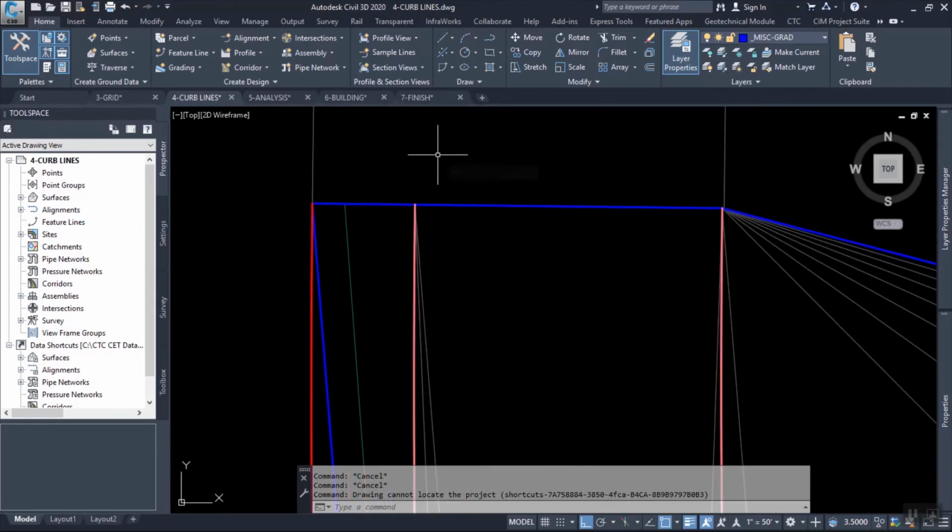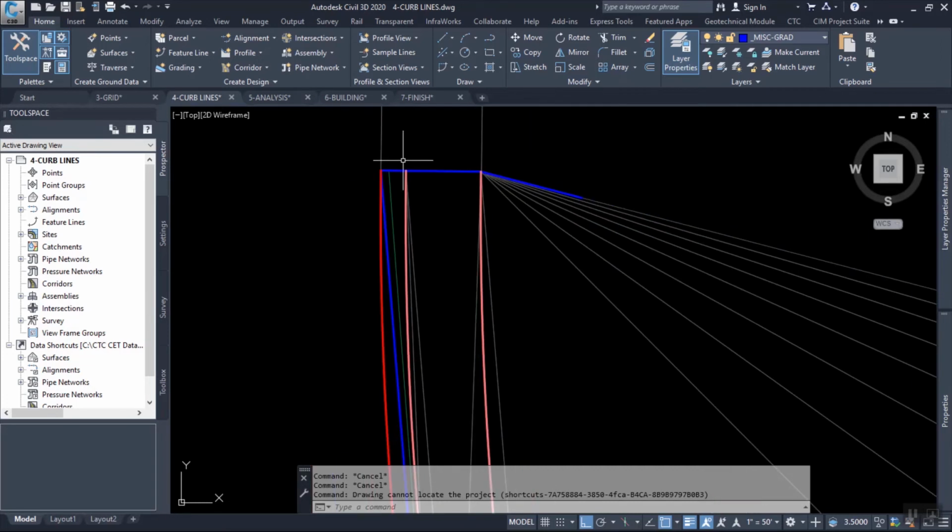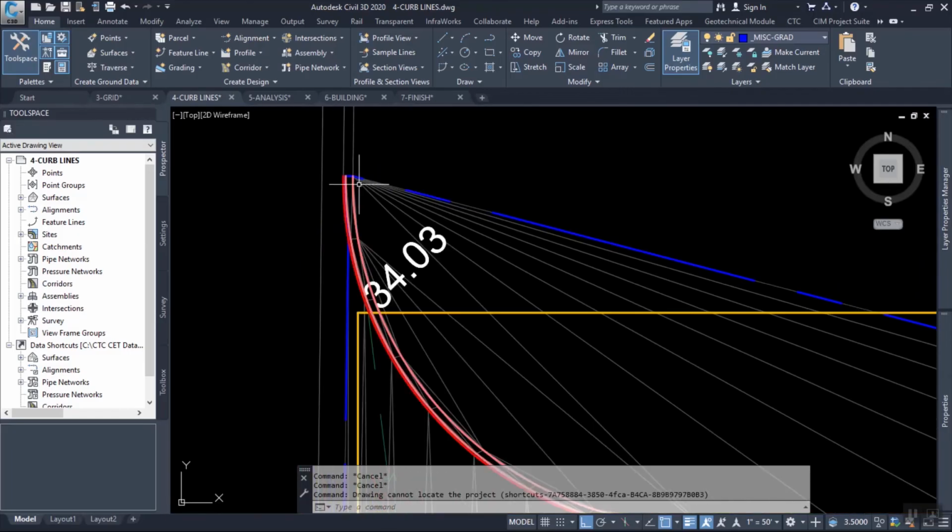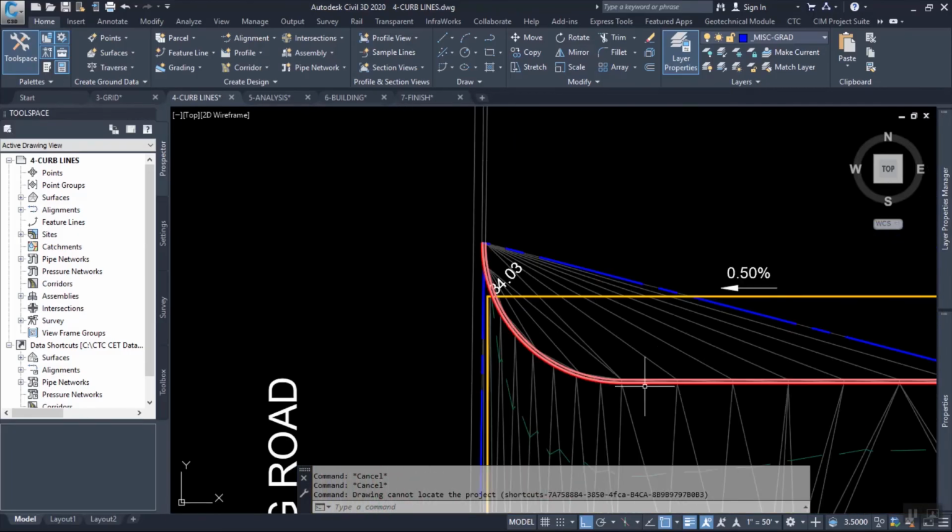If you have to do that for 12 points across the drop, would you use the point by point quick elevation edit, or would you rather re-offset the top face and top back? There are some other tricks you could do. Like you could break the feature line right here and make those curves relative to EG. You could put them in the same site and then make this feature line secondary and that primary.